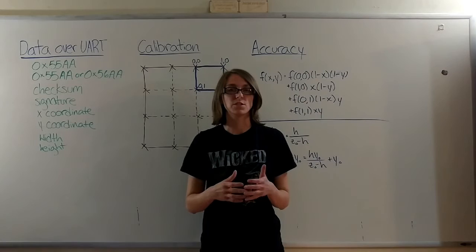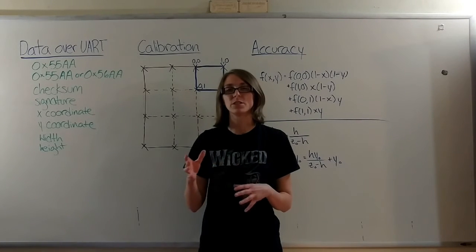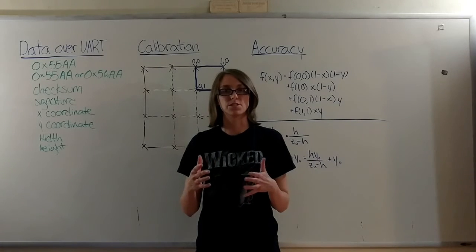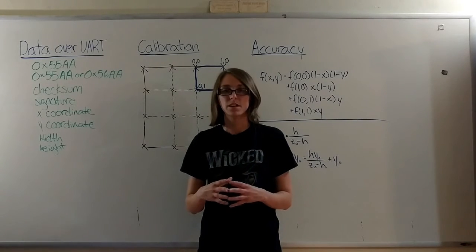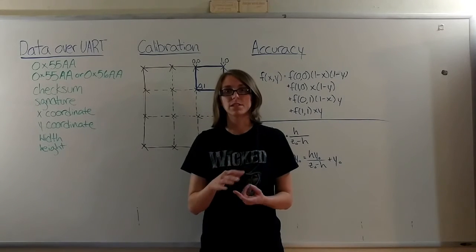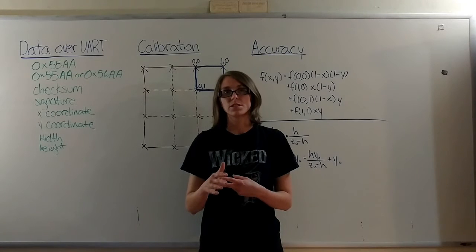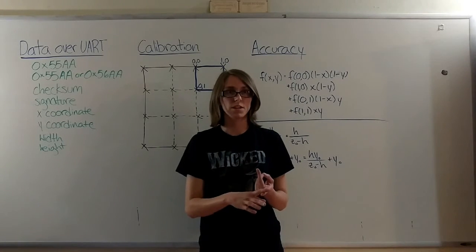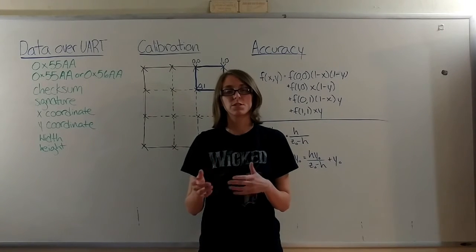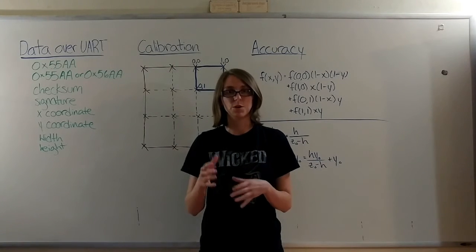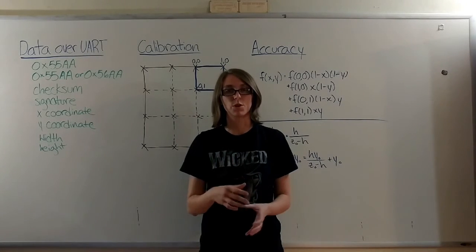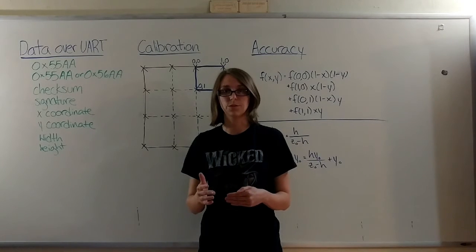It's best to use brighter or neon colors over darker colors in order for the sensor to pick it up better. Another advantage of using the Pixie camera is that it can collect two different types of object colors. It can detect a solid color or a color code. And a color code is two different colors, and that also contains an orientation, which is useful for the rover since we need to know orientation for the rover.